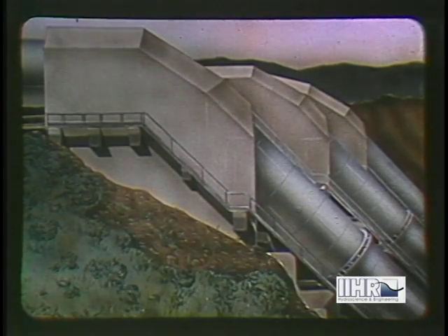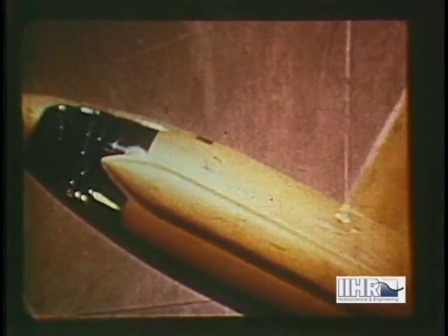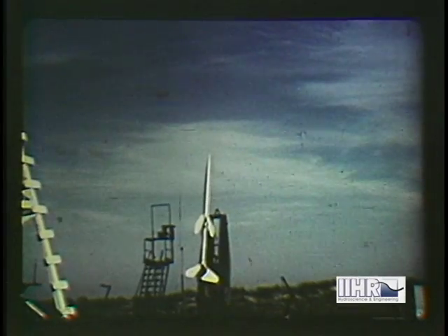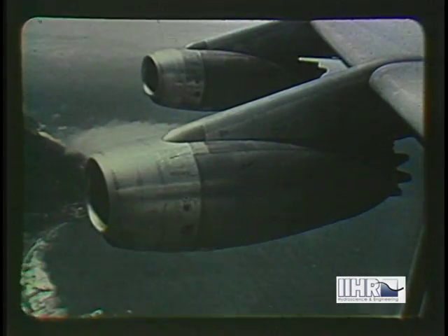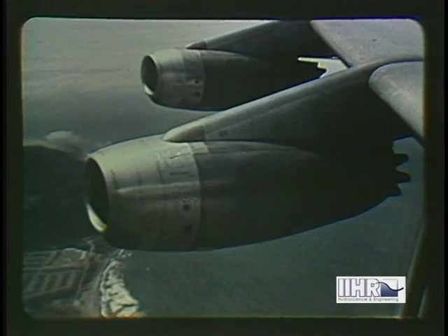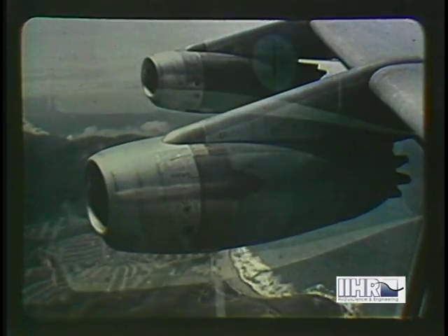If such forces are not statically counterbalanced, as in the sprinkler or this runaway balloon, then a useful means of propulsion is at hand. As a matter of fact, the reaction to jet formation is not only the most popular form of propulsion today, but in simplified terms, it is a noteworthy example of the intersignificance of the three flow relationships. Whereas space rockets, like the runaway balloon, carry their own fluid to eject, terrestrial jets, whether air or water, can take in at the front what they later eject at the rear in accordance with continuity requirements.